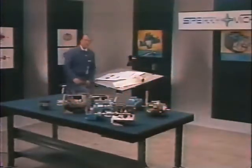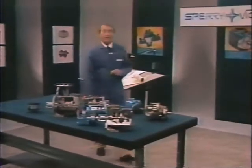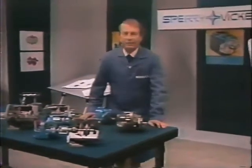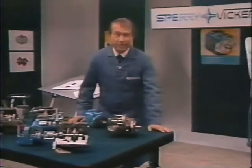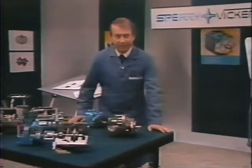Sperry Vickers gear pumps range in size from 7 to 50 gallons per minute at 1,200 RPM, although considerably higher drive speeds are permissible. They're available as both single and double units. Other manufacturers have gear pumps that are rated as high as 100 gallons per minute.